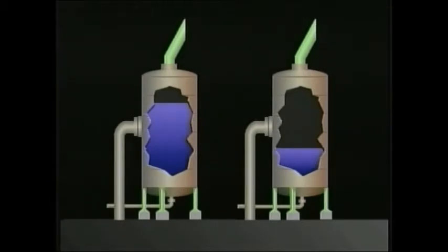Here again, we see two tanks, and both tanks contain exactly the same fluid. In this case, however, both tanks are at the same elevation. But notice that the left tank has a higher level than the right tank. This means that more work was performed and therefore more energy was transferred to get the fluid into the left tank than the right tank. So the fluid in the left tank contains more potential energy than the fluid in the right tank.